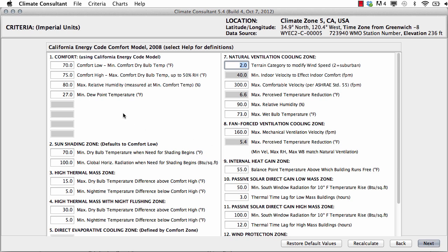You may want to adjust your comfort level temperatures, this is Fahrenheit temperature, based on your building use and activity level. For example, something that uses a high level of energy, you might be more comfortable at lower temperatures versus something that's a very passive activity, you might need to put these to higher temperatures. It could also be interesting to estimate what a difference it would make in your design if you were able to just change the comfort zone a bit.